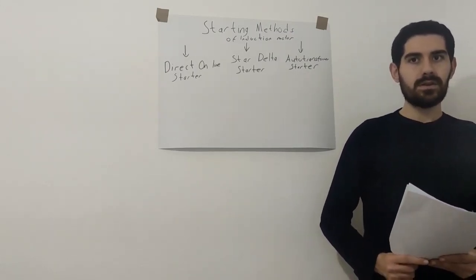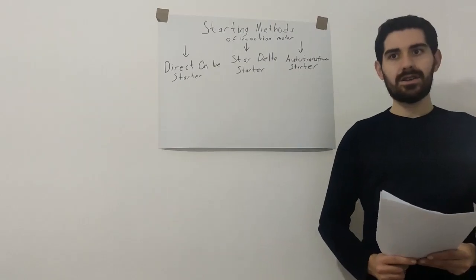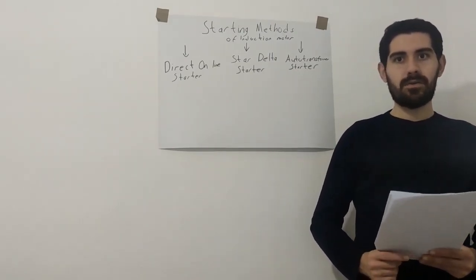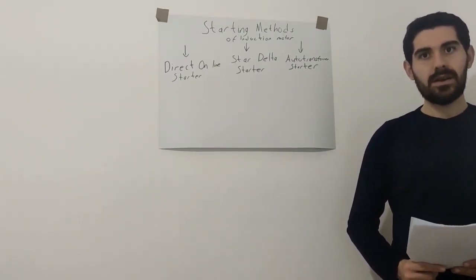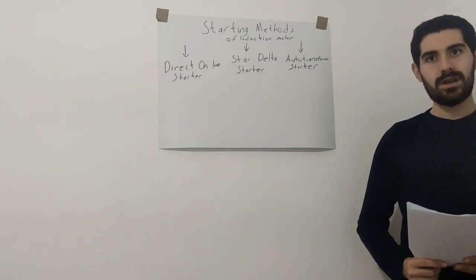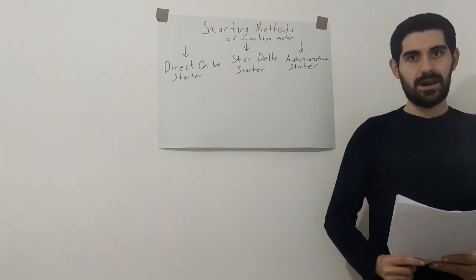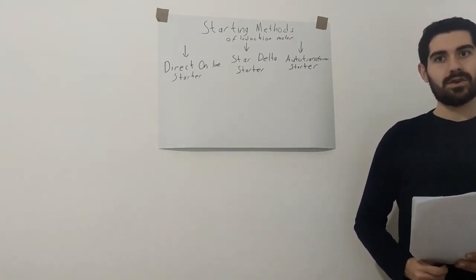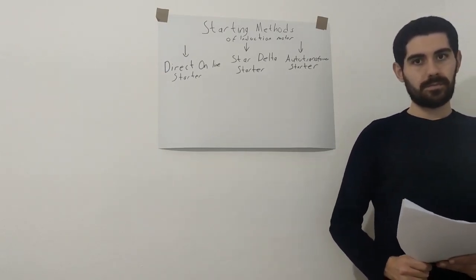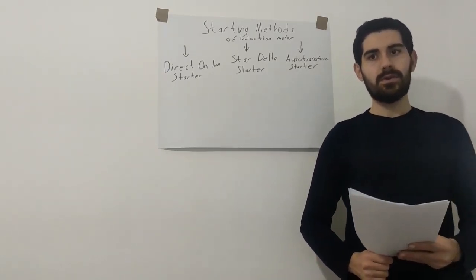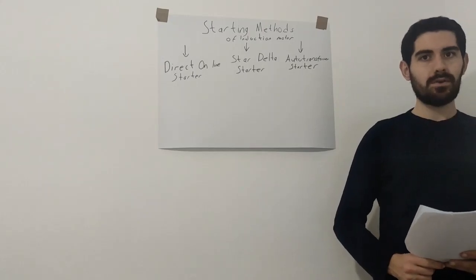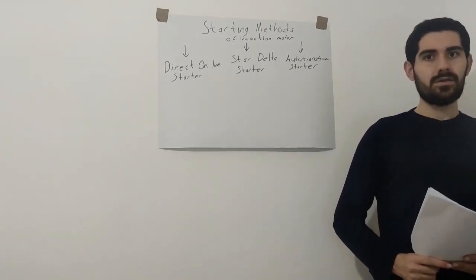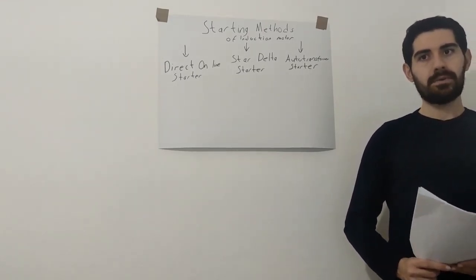The purpose of a starter is not just to start the motor, but it performs two main functions. One is to reduce the heavy starting current, the other is to provide overload and undervoltage protection. The three-phase induction motor may be started by connecting the motor directly to the full voltage of the supply.